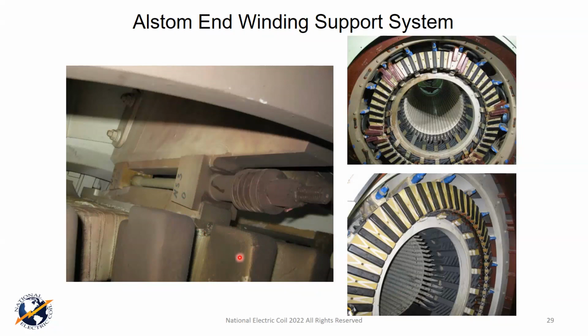And I said, "Well, sucks to be you. What is it? Where is it? What'd you do?" And it ended up being one of the larger 300 MVA, 21,000 volt, WX, WY machines from Alstom. And what happened is the failure occurred up in this region right here. And these phase leads that they have, when we looked at it, it just vaporized this one and it ate the corner out of this one.